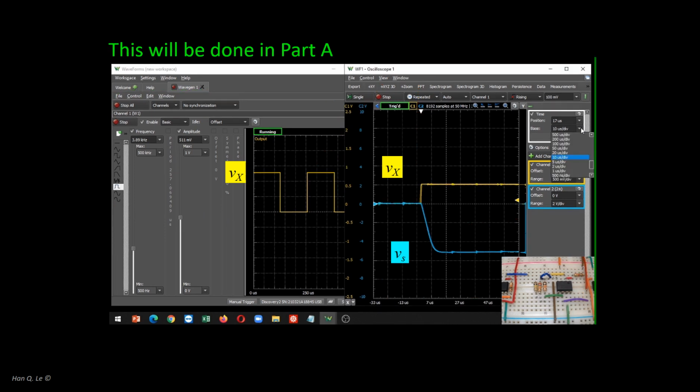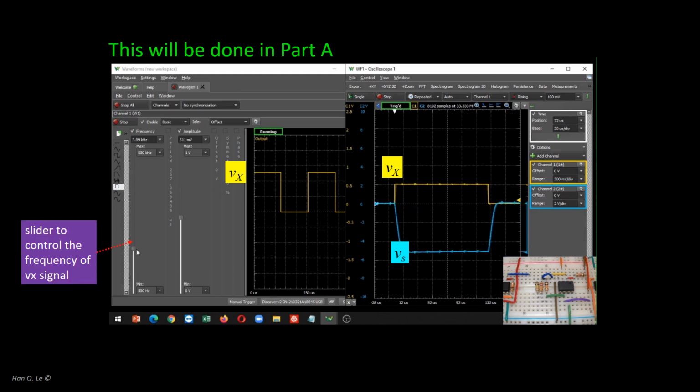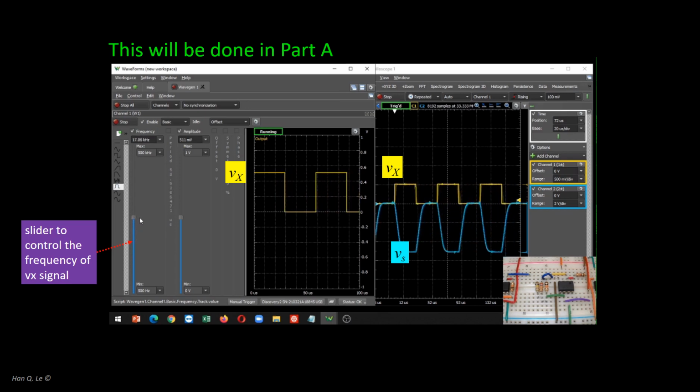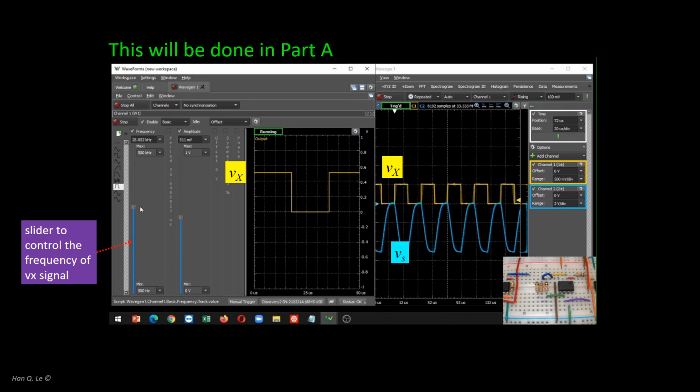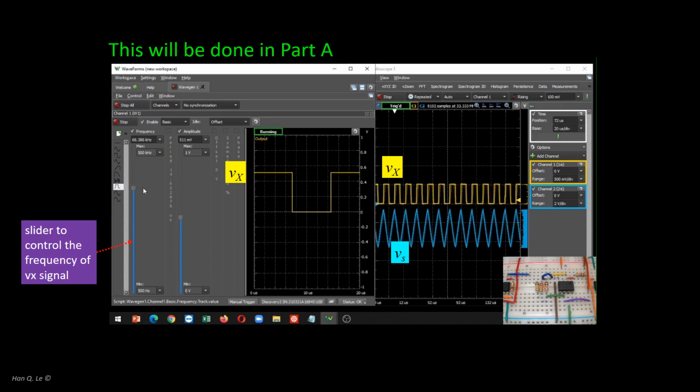The experiment shows what follows when the step change of Vx gets more and more frequent. When Vx changes so fast, the output Vs waveform no longer looks anything close to the Vx input. Hence, the voltage-dependent source model works, but only below a certain frequency limit. Like the car analogy in the introduction, how well an op-amp responds to high-frequency input is a figure of merit of the op-amp performance, like a car's acceleration, and this lab is a study of this frequency response concept.